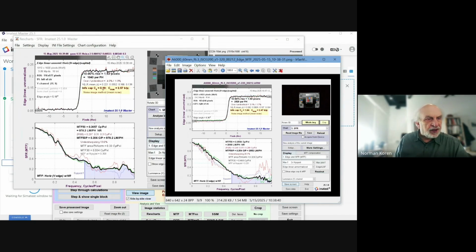And what you can see is that the MTF 50s are very close for these two images. There's a little bit of deviation, I think, because of the noise. The rise distance, again, they're close. There's some changes because of the noise. And the information capacities are also rather close. For the simulated image, the C4 is 1.04. It's 0.89 for the, actually, I have to look. This is the simulated image, and this one on the right is the acquired image. They're pretty similar, and it's actually hard to tell which is which.